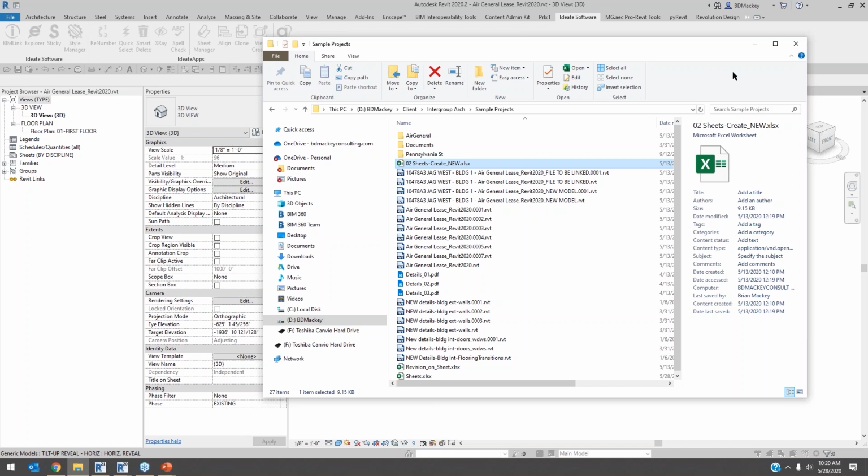The people weren't paying attention to work sets, phases, and all this stuff was kind of all over the place. So they went through and remodeled it to make sure it met their standards and everything, but they did not want to bring all the room information across, or manually, let me say, manually place all those rooms. We did the exact same thing. We exported the rooms with XYZ values, and then we did create new rooms with the same XYZ values,